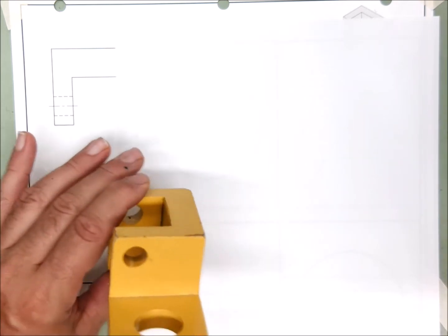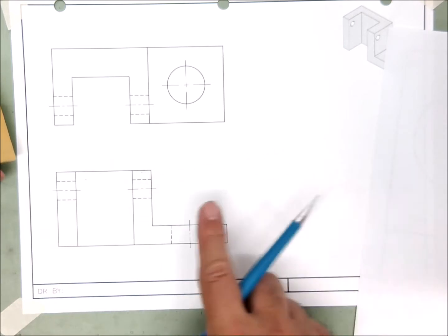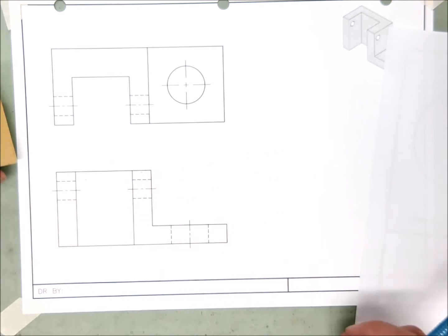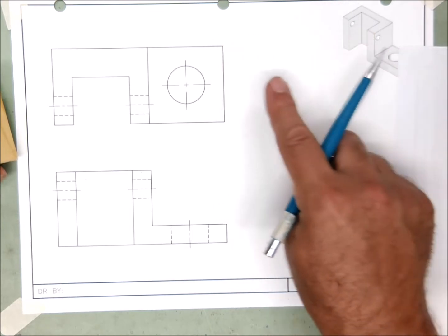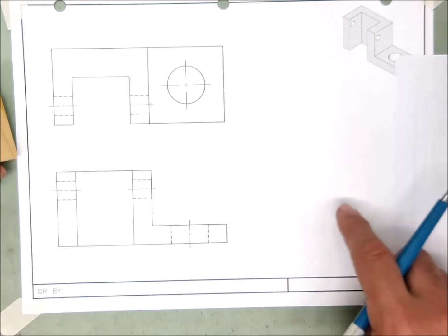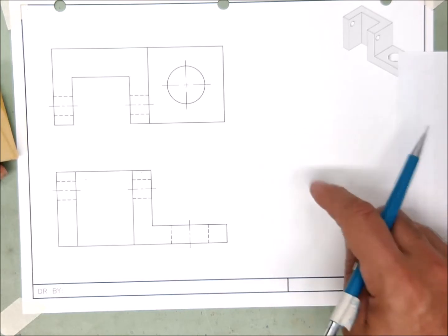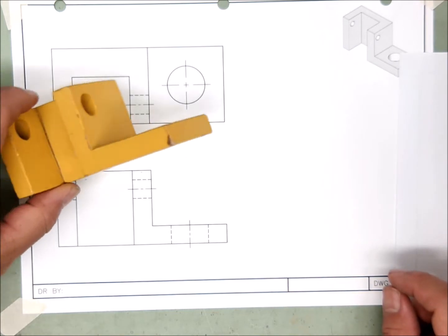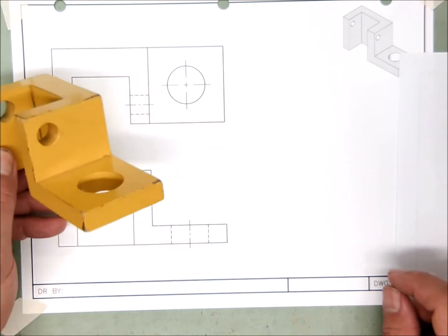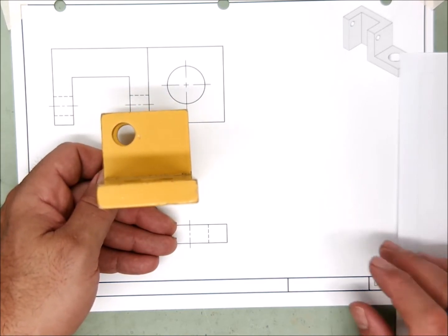You can't just project every corner and every edge from the front view to the side and then put a 45 line and project every corner and every edge from the top view. You know what you'll get over here if you do that? You'll get some crazy looking checkerboard, and it will not be the view that we're looking for. So instead, we're going to think about what we need. When you've got what you need firmly in mind, making the drawing is much easier.